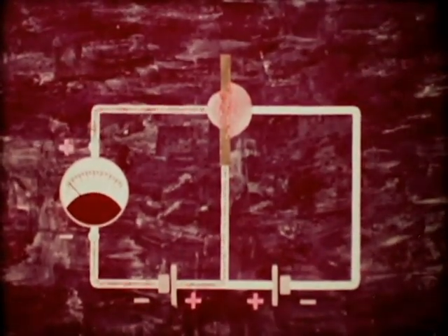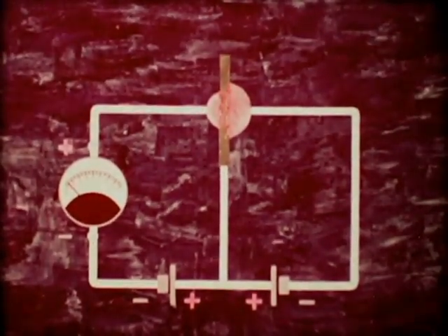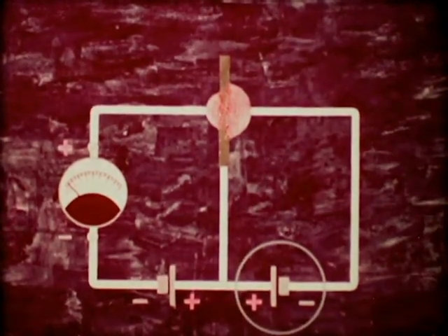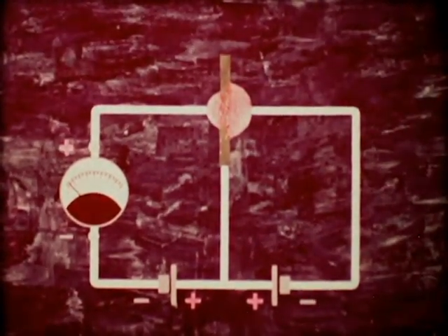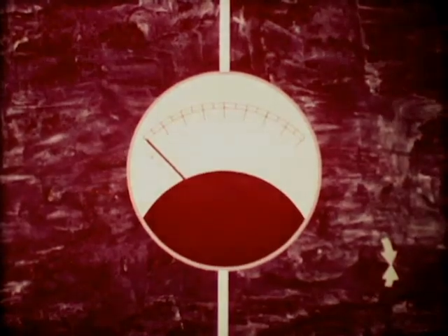A similar situation occurs at the collector-base junction, which is also biased in the reverse direction. In this case, the concentration curve of the electrons in the collector forms an angle with the horizontal axis, and the tangent of this angle is proportional to the collector current.